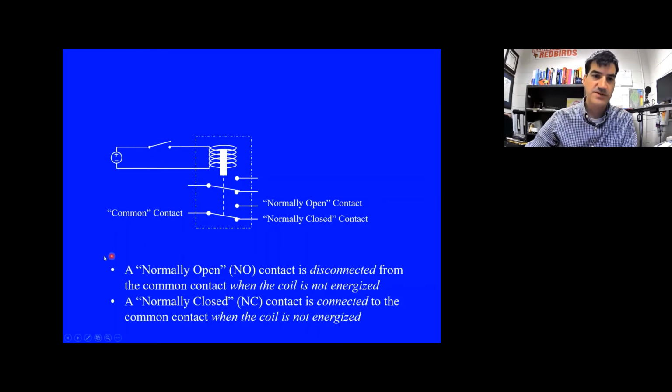So this is important. I mentioned this already before, but when we talk about the normal position, normally open, normally closed, that means the position of the switch when the relay is de-energized, like you just pulled it off the shelf or got it shipped to you in the mail. So it's not installed in anything, it's not energized. It's just what's connected when it's de-energized.